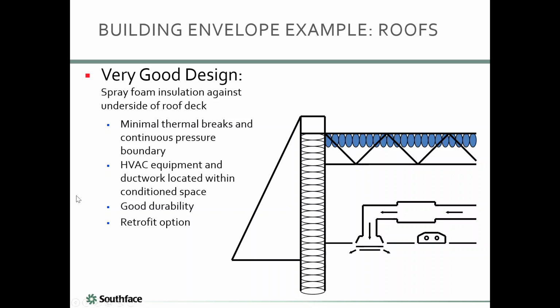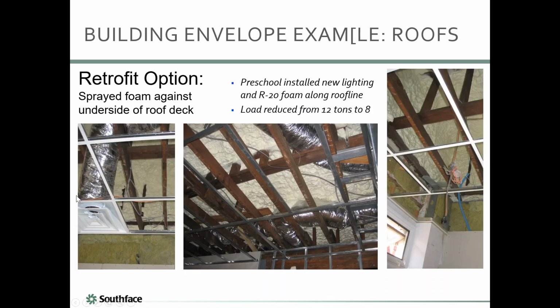I have a little case study building I was involved in many years ago. Pretty small building, a preschool, that they were going to put new lights in, and in the process of doing that, they were going to have to take out the grid ceiling. And I said, hey, why don't we get a quote on spray foam? And we ended up doing it. We did spray foam and new lighting. Not too much longer after that, they were getting new equipment, and we calculated the load reduced by a third, which is pretty significant. So the cost of the spray foam really was offset by the reduction in the mechanical equipment, and much better comfort and air quality and all that.